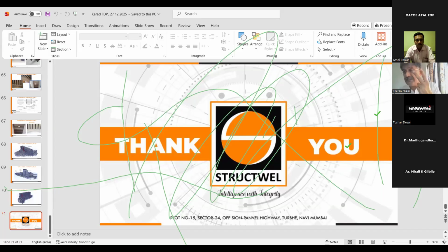The second technique which I use is like to like material. If there is wood there, use wood. If there is steel there, use steel. If it is limestone of a specific quarry, carry out petrography of that limestone sample, go to that quarry, get the material. If that quarry is closed because the yield is not there, I'd go and find out from surrounding quarries, you will get the stone. So first is just the right, second is like to like material.